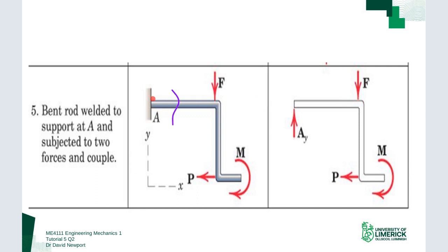So again, the process for all these is just to look at the system in isolation, say, right, if there's a cut there, and I try to push it in the y direction, push it up or down, pull it in or out of the wall, will there be a reaction force? Will it try and stop that? If I try and rotate in a clockwise or anti-clockwise direction, will it allow that moment? And that will tell me what's going on.